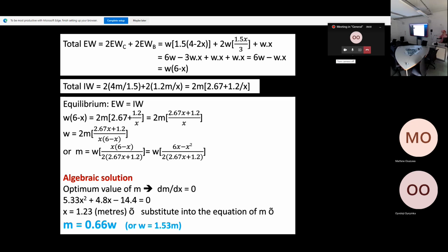I did explain last week that normally in practice, you will get the moment of resistance for the slab from the code. So you can use, for example, Eurocode 2, which is for reinforced concrete. You can get the expression of the moment from the Eurocode, because you know the size of the slab, the edges, the reinforcement, everything. So the code will give you M, and then if you use this equation here, you can predict at what load the slab will fail.